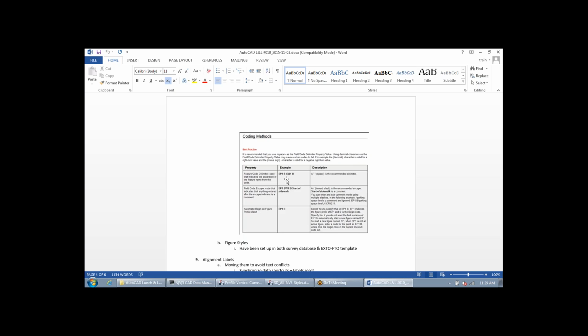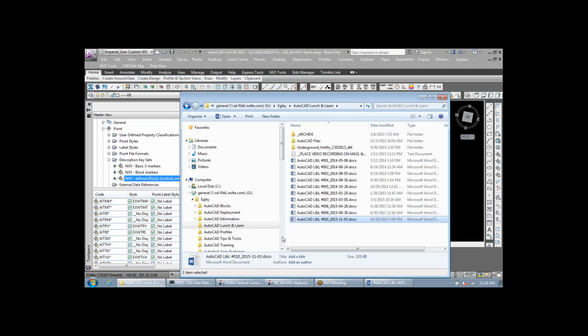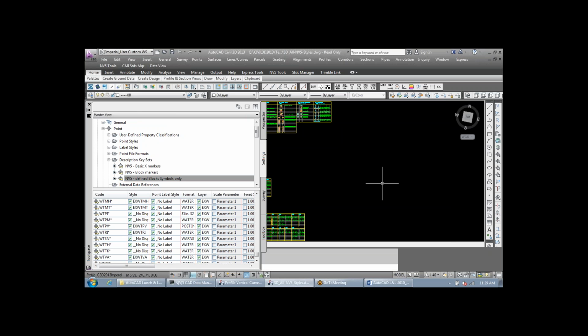You may need to move to individual import events. That's probably going to be part of that workflow. So there may be a real need to have two survey databases, one with just your all points file that you continually rotate out, and another survey database with all your individual import events. Keep that in mind if you're after survey figures.